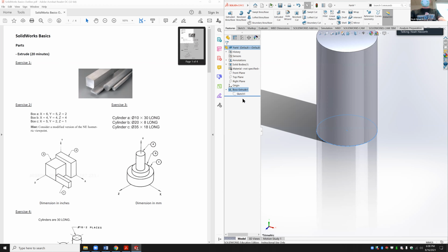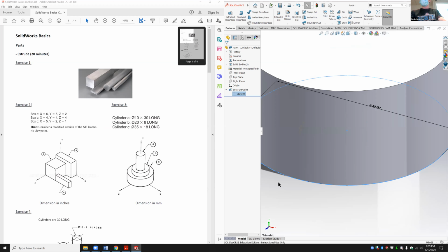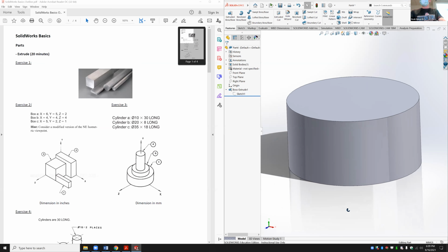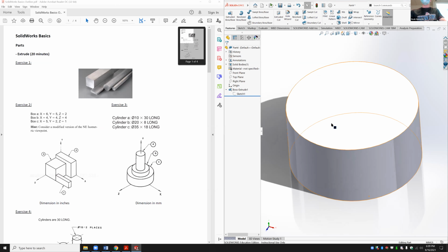One of the nice things about SolidWorks is I can click on the sketch, edit it, and change this to the right value, which is 35. Automatically my cylinder updates itself. At this point I really ought to zoom out, and I just zoomed in, but there we go. Hopefully you have a better mouse than me, and zooming in and out is easy, but for me it's currently not.